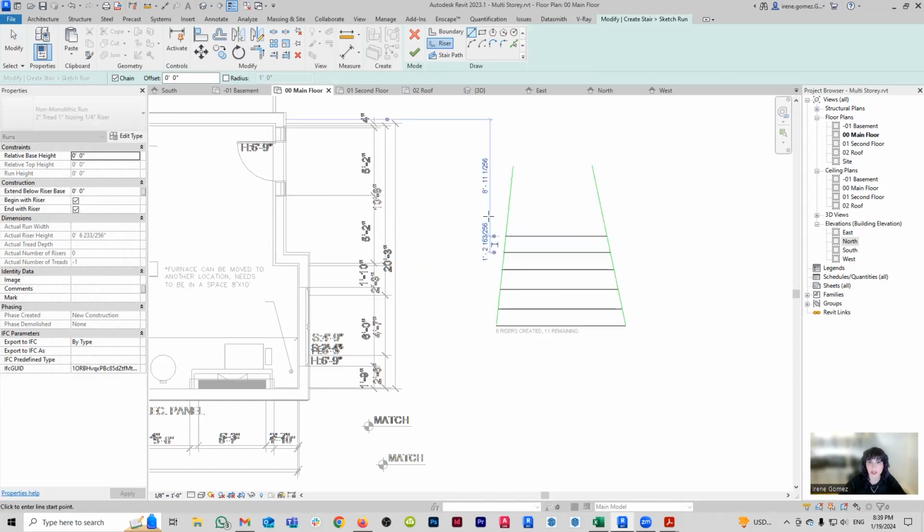The thing that you need to understand is that Revit will always determine how many steps you need. You don't decide that. Revit decides it based on the formula of the total number of steps. So I'm fudging it here and making all sorts of shapes of steps just to make sure that I get the total number of steps that Revit is requiring for me.